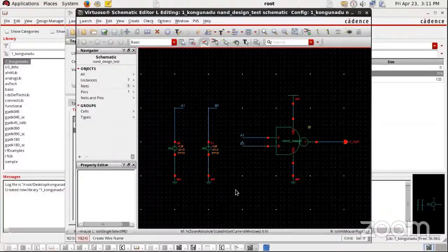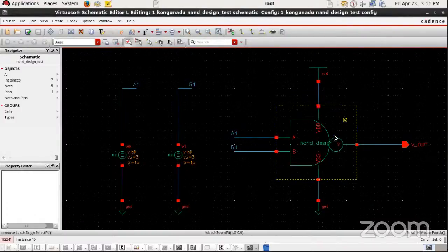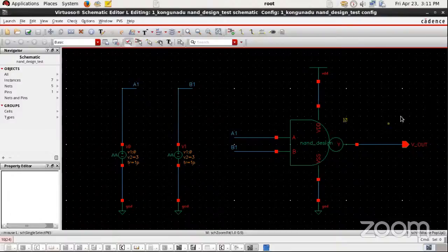This should bring back your test circuit. After creating the configuration, you should open the test circuit from the hierarchy editor. To confirm whether the parasitic resistances and capacitances are imported or not, we can peek down this hierarchy.